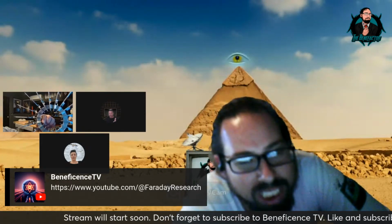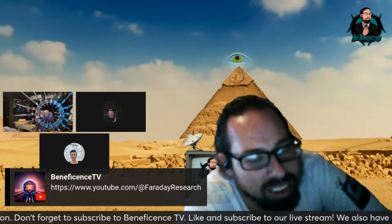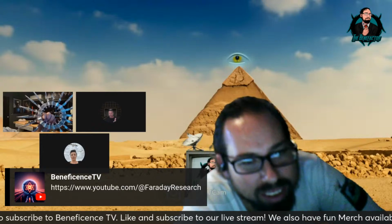these little pieces right here, they all break off because they're junk. Too thin. Yeah. He tried to slice it in half, and he shouldn't have. He should have just notched it, and it made for a junk print. Or you could put a giant raft under every one of these when you print, which basically means you're going to waste a bunch of PLA for no reason.